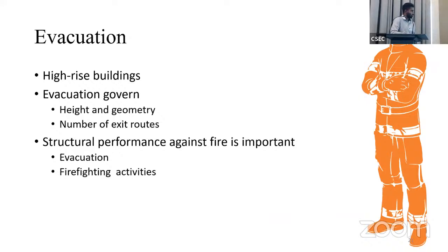In high-rise buildings, evacuation is governed by these things: heights, geometry, number of exit routes. I will discuss these points in the next few slides, along with the structural performance as I discussed before. All the people inside the building have to evacuate before it fails. So we have to ensure that the structure remains standing until the final person evacuates from the building.